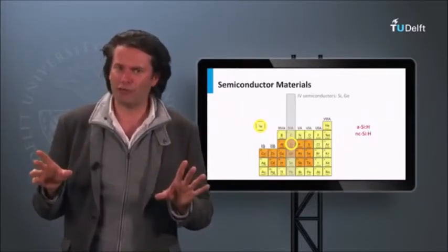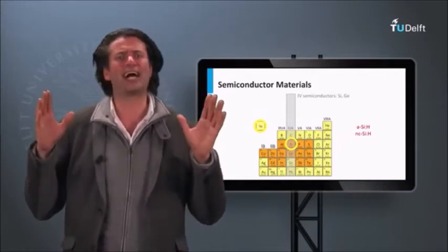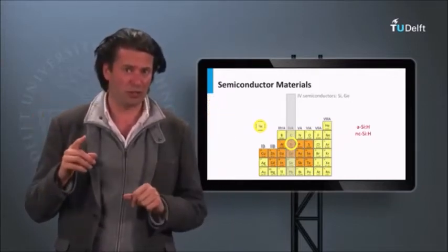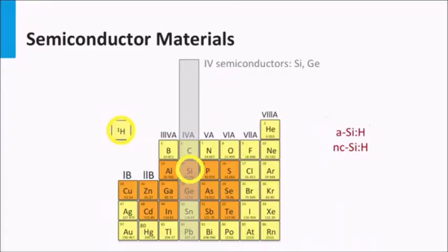So the first question we have to answer is, which type of silicon alloys are being used as an absorber layer? The typical lattice structure is either amorphous or nanocrystalline. Nanocrystalline is also called microcrystalline in the literature. In a moment I will come back to how these lattices really look. a-dash is the abbreviation for amorphous, and c-dash is the abbreviation for nanocrystalline silicon.